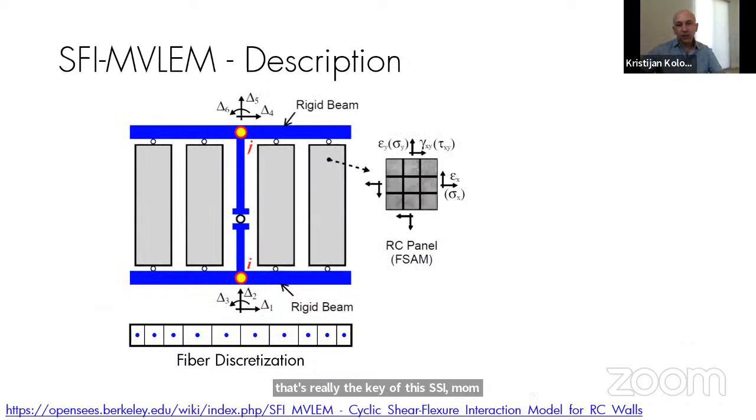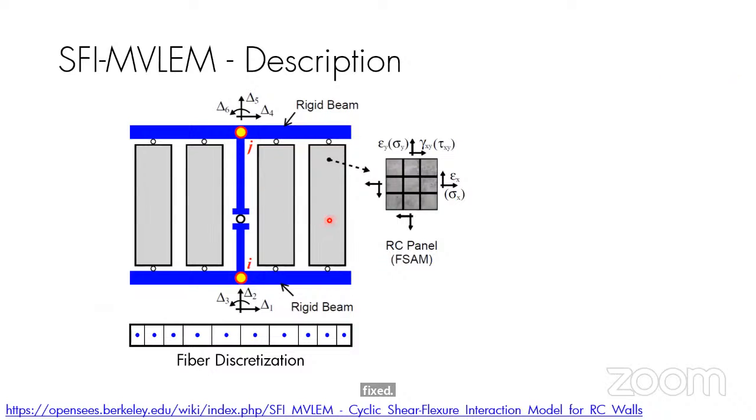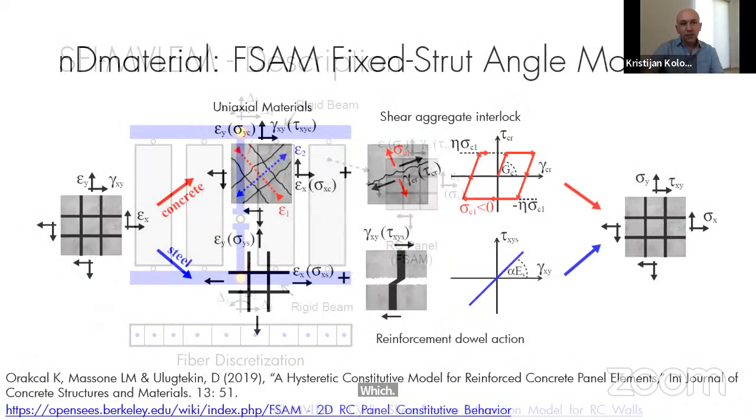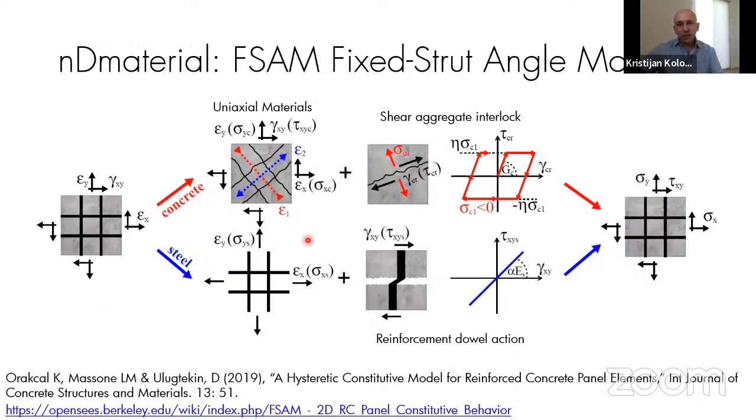So particularly in OpenSees, we implemented this fixed strut angle model as this reinforced concrete panel behavior, which is, again, also available as an ND material. So this ND material, just one slide about that. It's a fairly complex material model.